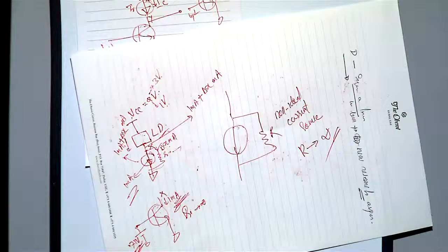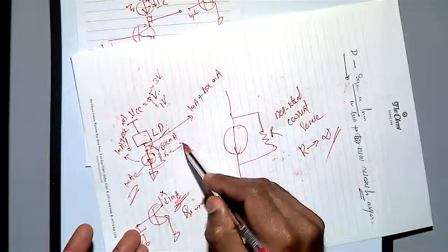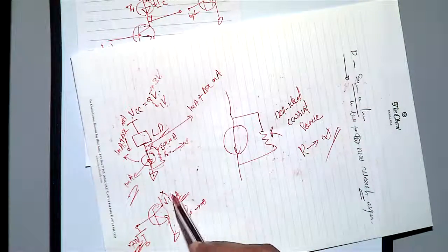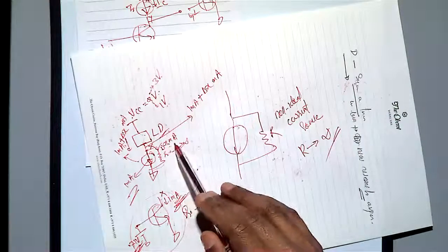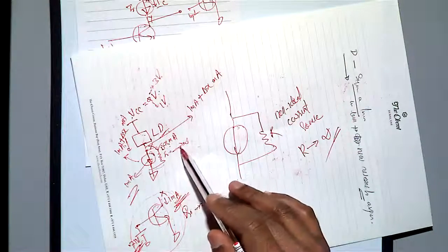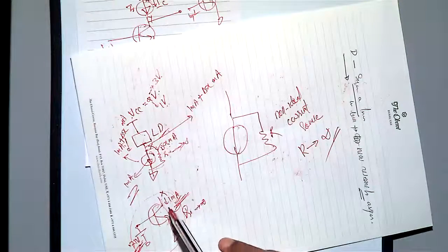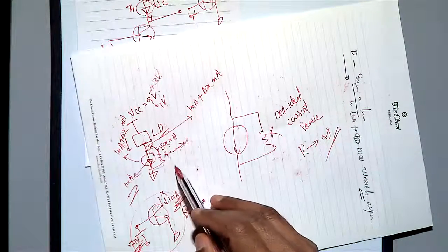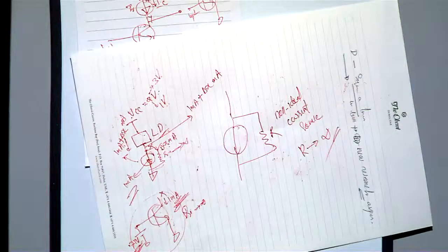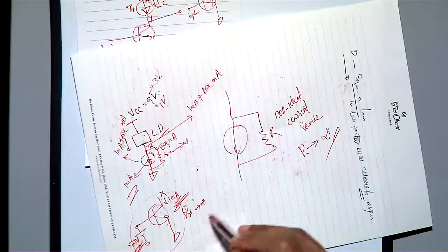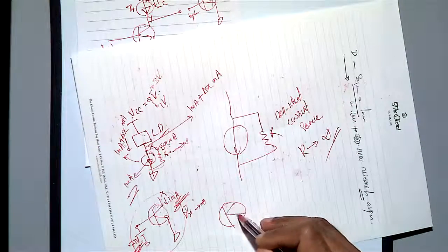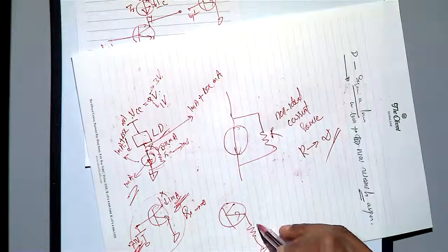So the circuit will adjust it. So our aim is how to make this RO infinity. Using one simple transistor, if I connect here, this RO is not going to be infinity, it is a finite value. But then we have studied, we can increase the value of RO. Do you remember that? Yeah, add another transistor, or instead of this one, you are right, simply connect one RE.